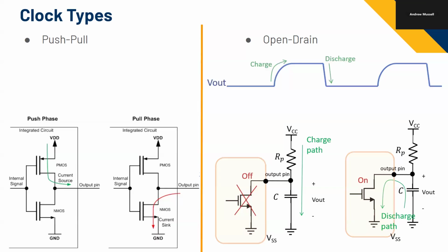This one, you have to drive the gate and the source. This has to have full range. So it has to be able to drive both of these inputs to the MOSFET from the internal signal. On that one, you only have to drive one MOSFET. So it's the difference between having to drive 2 FETs versus 1. What other trade-offs are there?